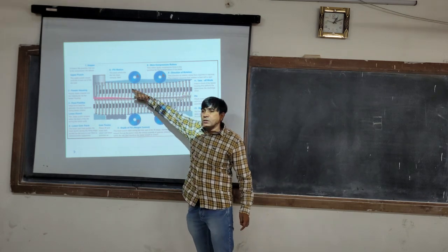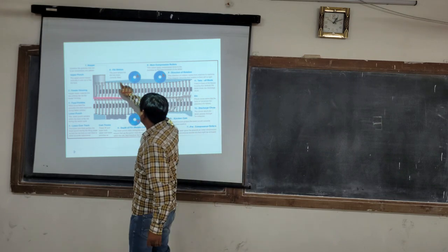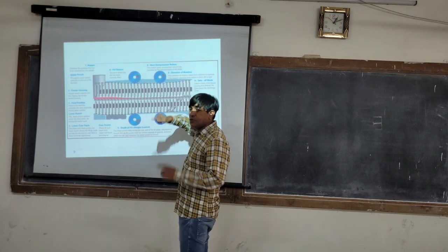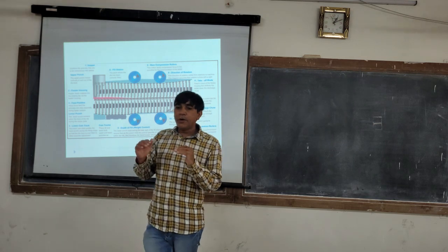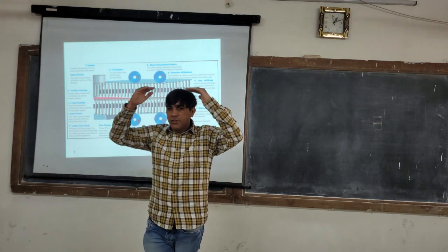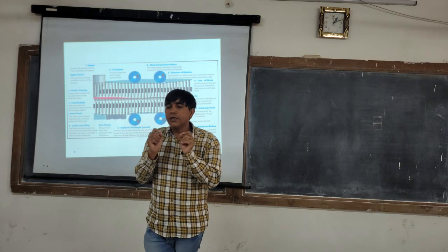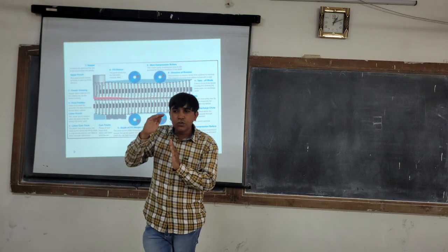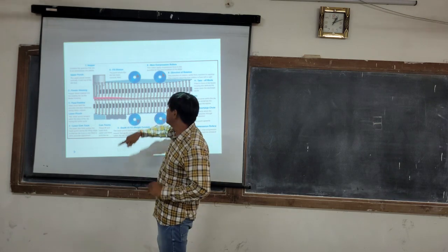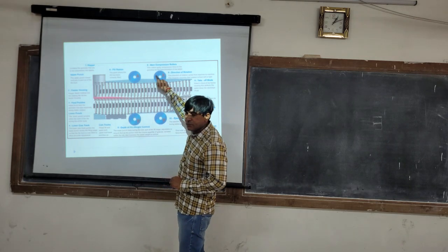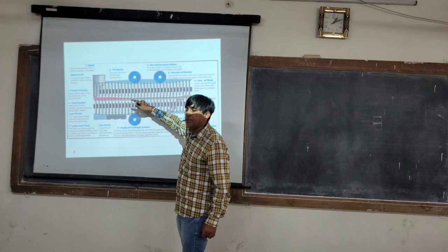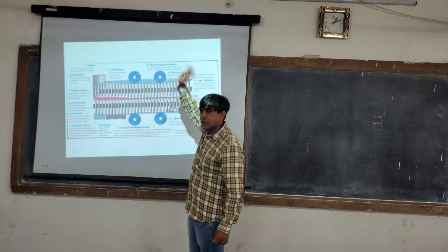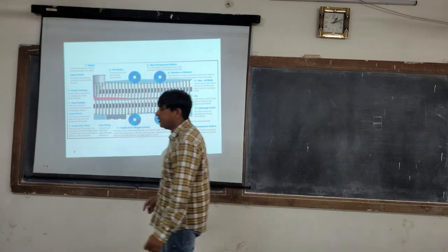The upper punch is guided by this track. At the top, there is a track which will guide the upper punch. During most of the time, the upper punch remains in a raised position. Only during the compression, it moves to the die cavity, compresses, and again moves back. So when it is under the compression roller, it is entering the die cavity. The rest of the time, it is raised above by the track.